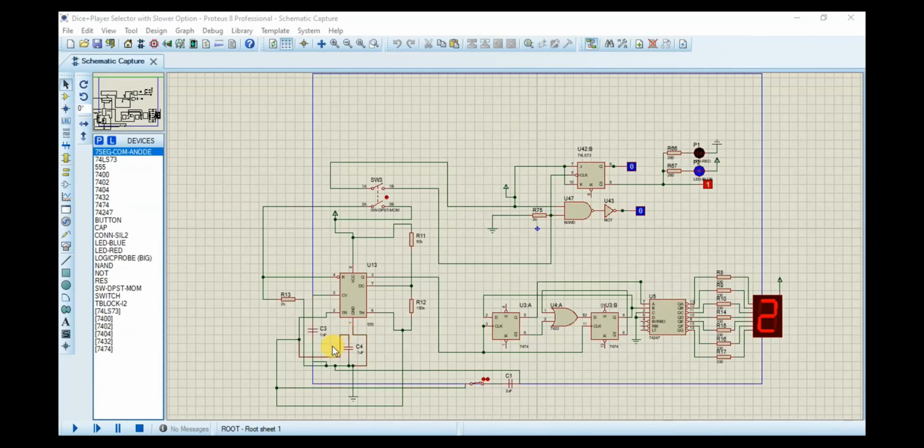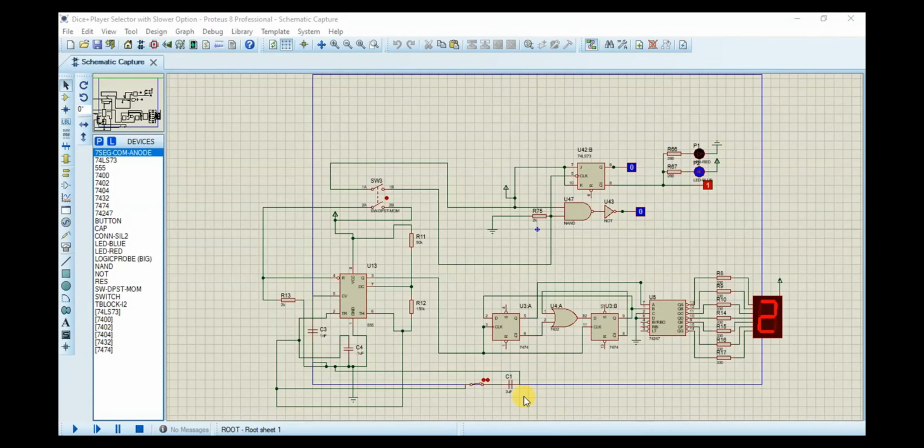Here, an external capacitor charges and discharges through resistors, determining the frequency and duty cycle of the output pulses. The two resistors are used to calculate the frequency of this IC timer. We can use a simple formula to determine the frequency of the 555 timer. We have used a large capacitor which lowers the frequency compared to the previous one. Using this capacitor, we can slow down the dice frequency and observe its operations.